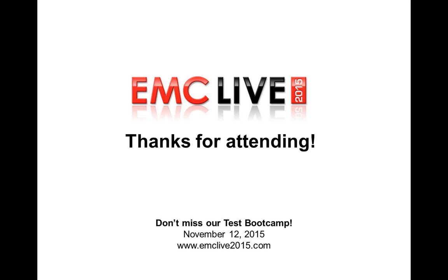Great. Here's another question. What about the electronic devices with plastic enclosures? Are they unshielded? So there are different solutions when using plastic. One is to paint them inside with conductive paint, but usually the other solution is to work at another level. To shield, as we saw before, we can shield at different levels. If we have a plastic device, probably we have the shielding at a PCB level or at the component level. If these levels are properly shielded, then we can use a plastic enclosure without problems.